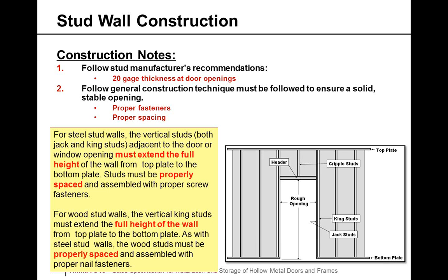That's critical when you're looking at stud construction. If you're looking at job sites, particularly in current construction where everything is fast-tracked for steel studs, a lot of these studs are really out of plane and crooked, and any type of photography when you're inspecting a job will help offset any type of future back charges.